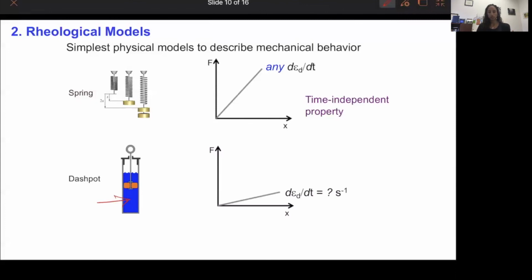So for example, if we apply a force at a relatively low frequency, at a low deformation rate, we might have a stiffness that is shown here. And as we increase that loading rate, what we're going to see is the stiffness that we measure out will also increase. And so we can continue increasing our loading rate to get even greater stiffnesses or stiffness behavior.